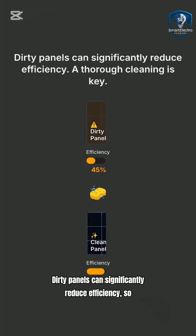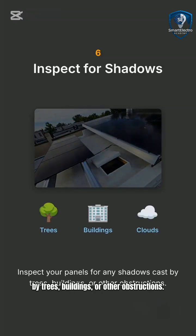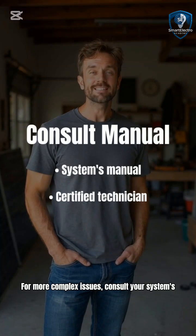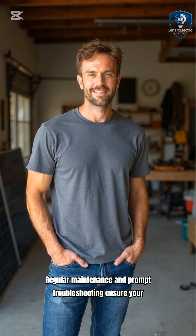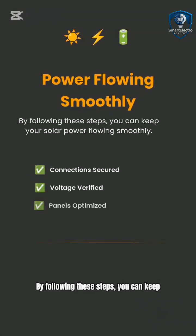Dirty panels can significantly reduce efficiency, so a thorough cleaning might be necessary. Inspect your panels for any shadows cast by trees, buildings, or other obstructions. Even partial shading can drastically impact the overall performance of your solar array. For more complex issues, consult your system's manual or a certified solar technician. Regular maintenance and prompt troubleshooting ensure your solar system operates at peak efficiency. By following these steps, you can keep your solar power flowing smoothly.